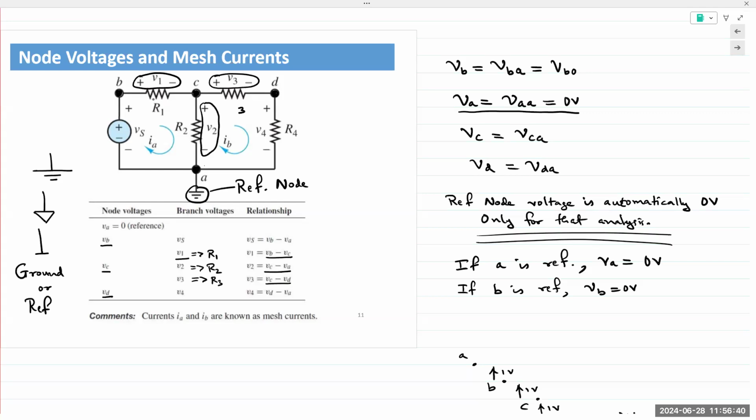So the question being asked is, if the polarity was flipped, would we use summation? The answer is no. It would always be a subtraction because voltage is a difference between 2 points. So for there to be a difference, one point has to be higher than the other one. And that comes from the assumption of the current direction. That comes in the next step.